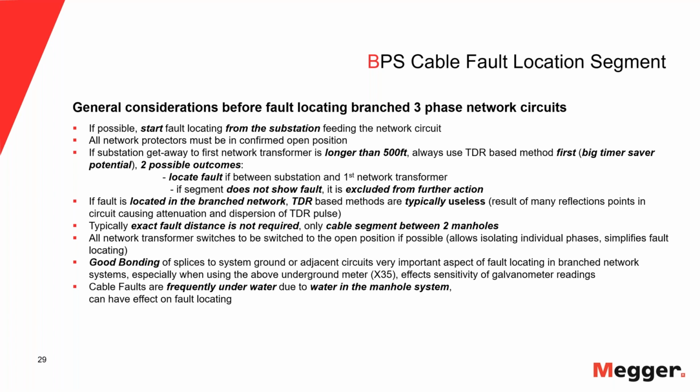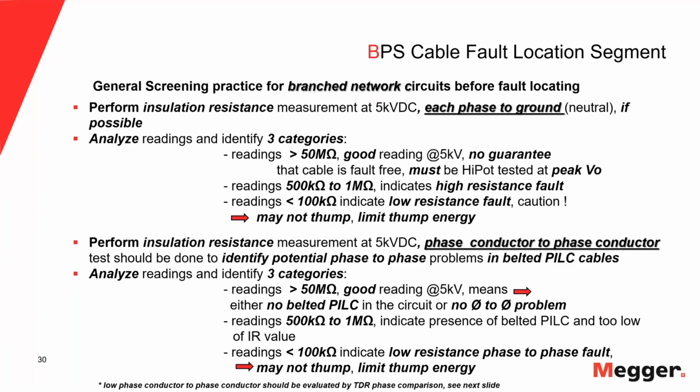Now, if you have a poor signal, it could be that the unit won't pick up anything. And that's what I hear sometimes. People say, well, we use it, sometimes it works and sometimes it doesn't work. That is a clear indication of the bonding condition in your circuit. So I just want to point that out. It's not the equipment. Every piece of equipment has limitations, and it's designed for certain things to do.